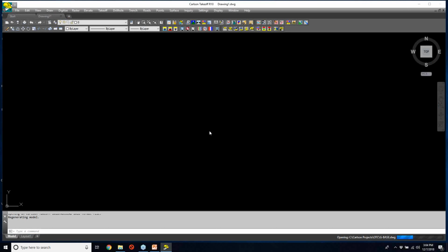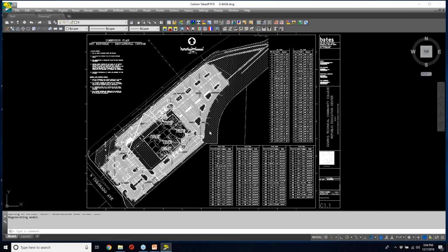because one of the things that was sort of slowing me down a little bit this past Tuesday was the amount of hatch material that was in this actual PDF. And I sort of showed some tips and tricks for the Takeoff Suite products found inside of the IntelliCAD engine. And one of the things that I want to do is get rid of the hatch entities that are found inside of this particular drawing. And the IntelliCAD engine does provide a nice filtering mechanism to get rid of the hatch entities.